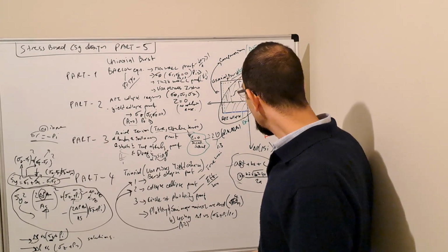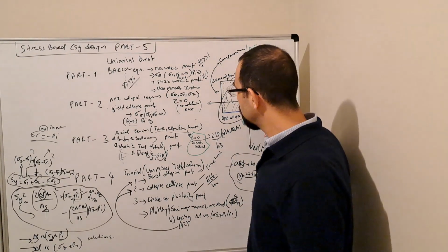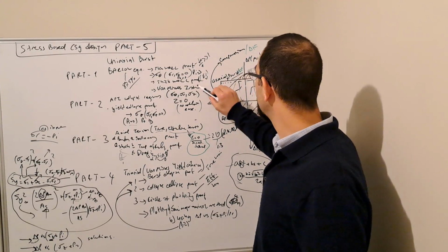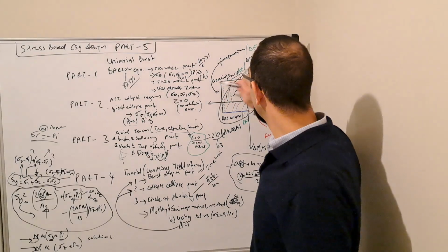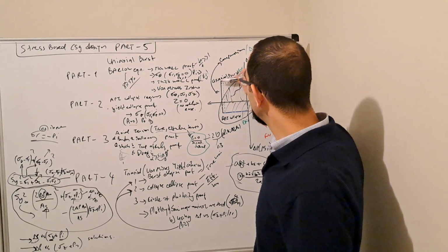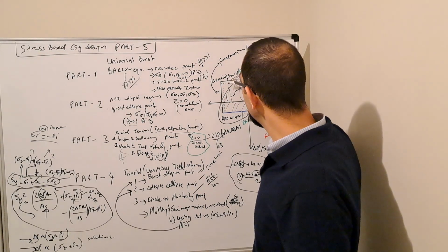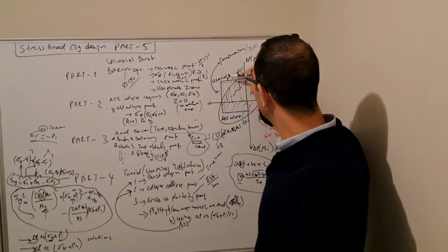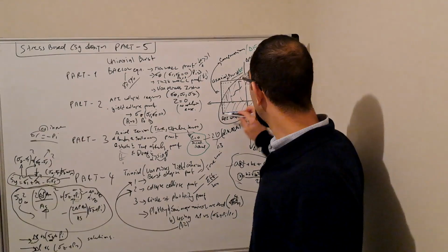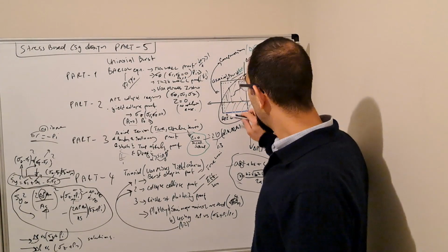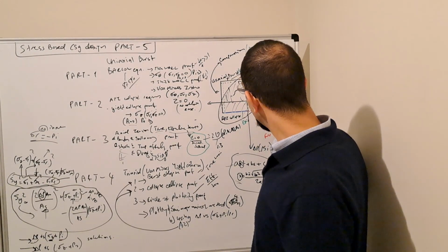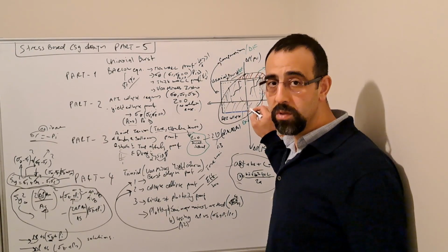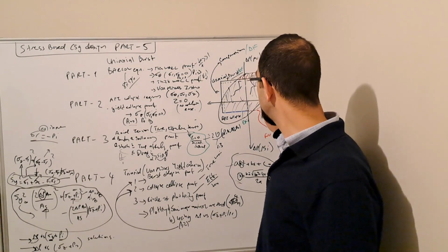So when we come to this design limit plot, to do a recap. On part number 1, we covered uniaxial burst rating. We proved this one, and then we showed that the design factor, you could see it can come down if you increase the design factor. Part number 2, we covered this part, and if you remember, this part was a pure effect of tension on the rating of the collapse value.